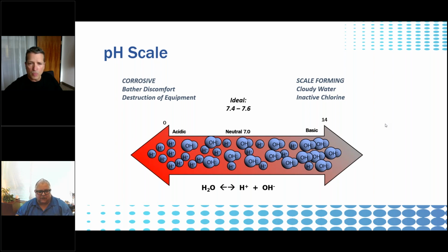So the higher your pH goes, the more chlorine that, as I call it, lays around on the couch watching Oprah all day instead of going out and doing the job that it's supposed to do. So then you would have to compensate by creating even more chlorine to try and overcome that. For example, at a pH of 7.5, chlorine is 50% active, 50% not active. That's a great balance. That means you've got chlorine working and you've got chlorine still kind of waiting to be activated, so you don't use everything up at once.